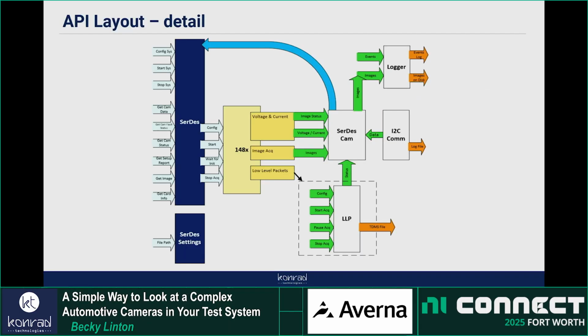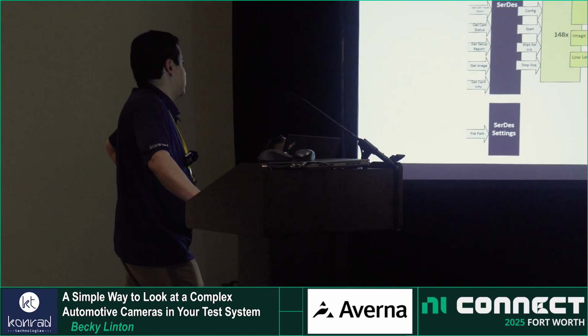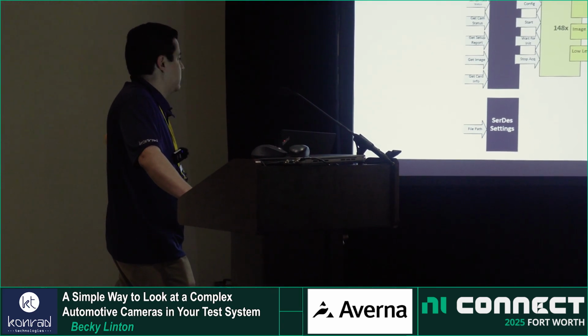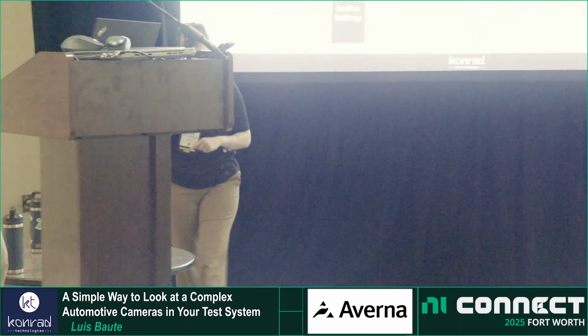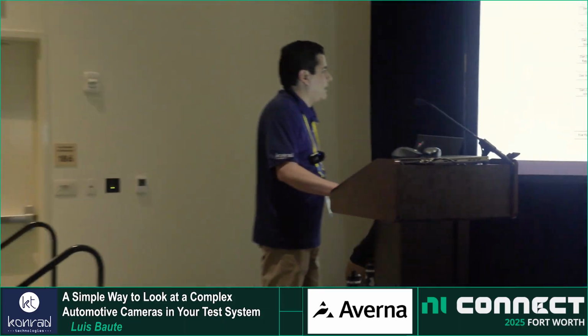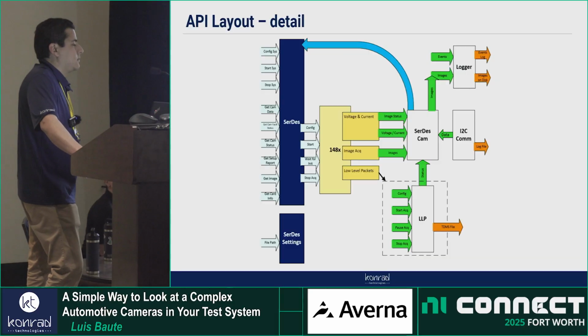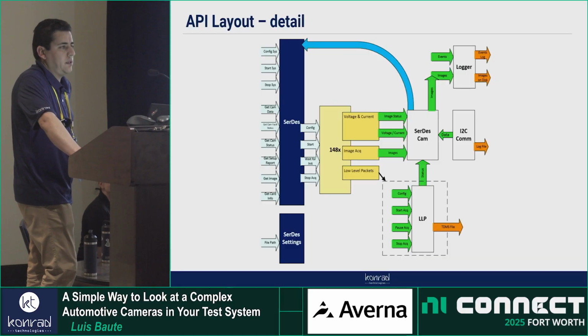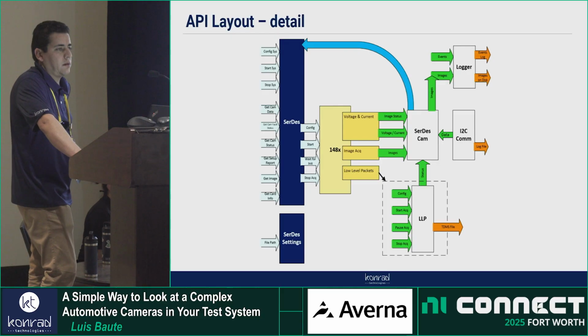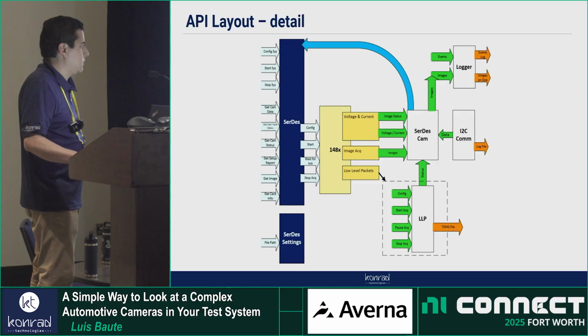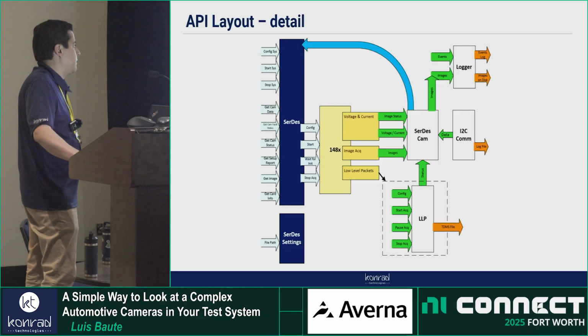So that was kind of one of the reasons we went with DQMH, the ease of use to add clonables, because we didn't know if the customer was configuring 10 channels, 24 channels, whatever. So I wanted to mention, I know he said module, but I want to be clear, those are DQMH modules. Yeah, these are DQMH modules. And yeah, customers started requiring new stuff, and it was easier just to add new modules. And we just started with clonable modules because we knew there were going to be multiple cameras.